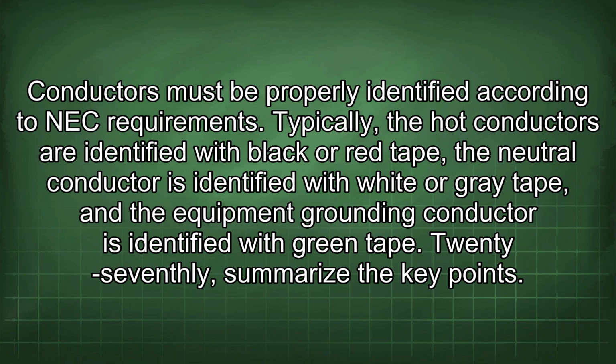Conductors must be properly identified according to NEC requirements. Typically, the hot conductors are identified with black or red tape, the neutral conductor is identified with white or gray tape, and the equipment grounding conductor is identified with green tape.